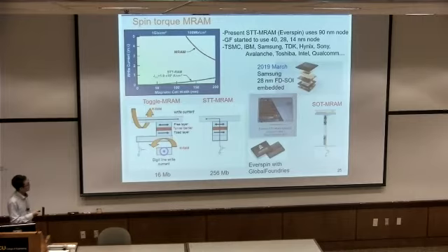And then later on, people spent quite some time to understand this spin transfer torque phenomenon, in which we can just inject charge current into the junction, and depending on the charge current, you can switch one layer to the other. So as you can see, the structure architecture is very simplified compared to this field-based switching.